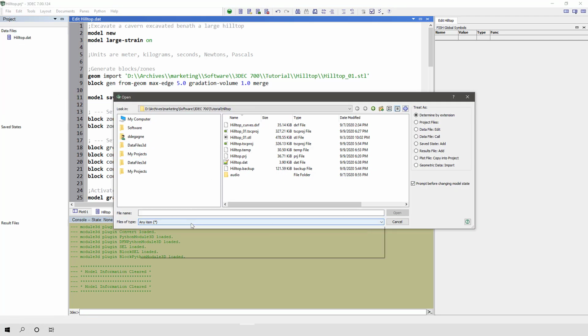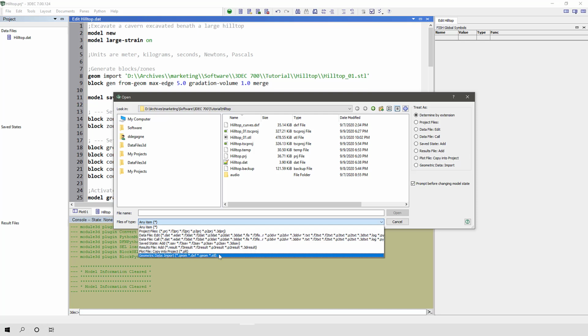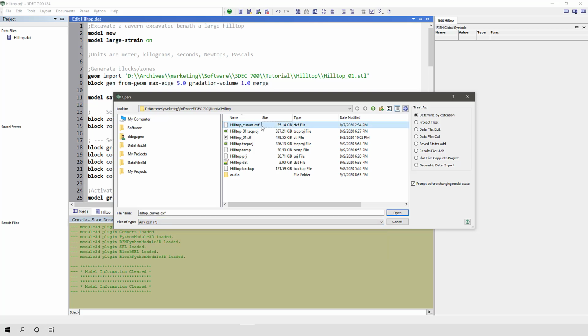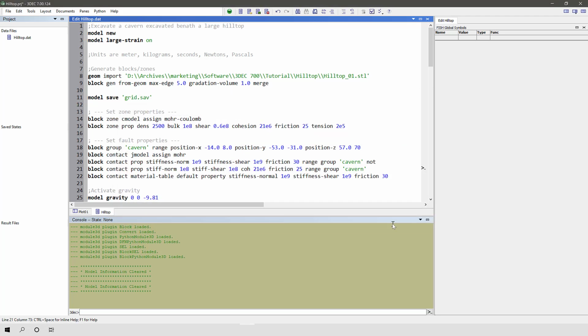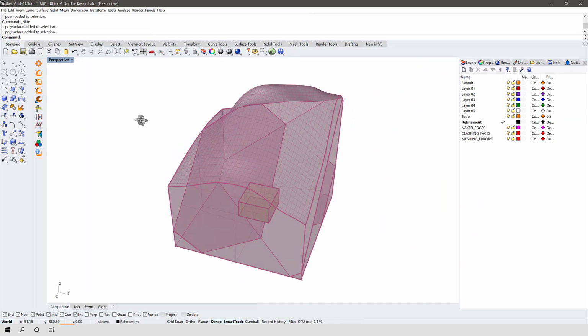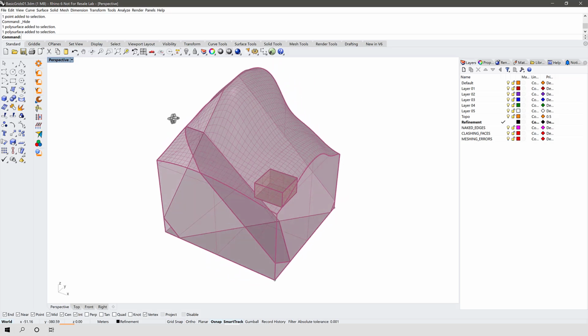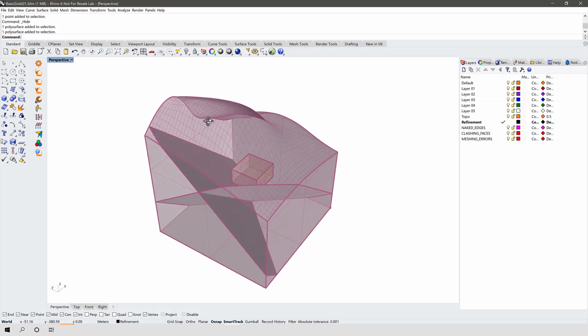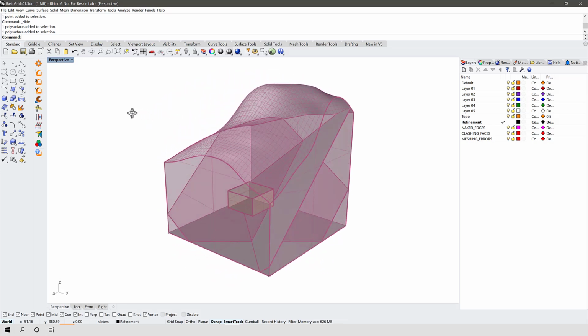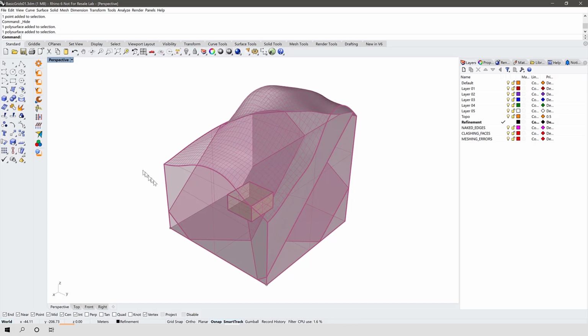Geometry can be imported into 3DEC as either DXF, STL, or ITASCA geometry formatted files. Such geometry can be used to generate blocks and zones or for plotting as a reference image or contouring of results. The model geometry was first created using CAD software, in this case, Rhino 3D. Here we see a hilly topology and two major, intersecting faults with a cavern situated between them. Note that this object is a single, closed volume, watertight entity.